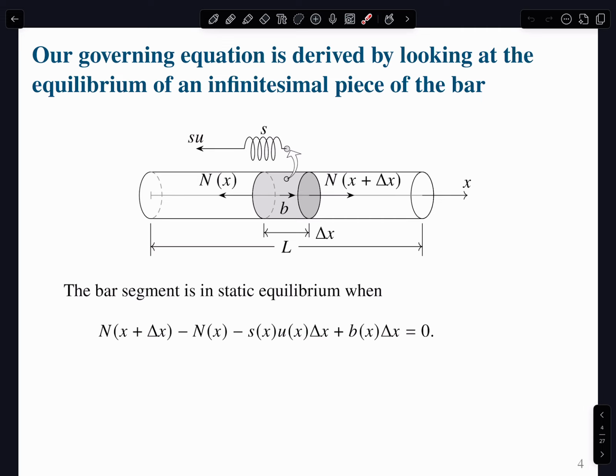So imagine you have some pile in the ground, and we try to pull that pile out of the ground. Well, imagine that you're going to have some resistance, right? So imagine that that resistance is transformed into a force that is proportional to some spring per unit length, right? That is basically what I try to do with this s. So every point around the bar has some resistance to be pulled out, basically.